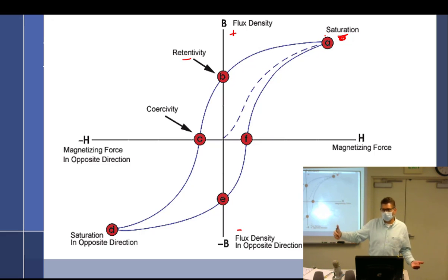Now, some material, like these harder crankshafts or things that are hardened that have high retentivity, if the retentivity is way up here equal with saturation, then you've got it made. You can keep doing it over and over and you don't have to apply the power, but that's not usually the case. Usually retentivity is a little less than saturation. So anyway, we apply the power. We can apply the fluid at that point. We've done it at the saturation level. Remove the power, it pops down here to retentivity, and there it is, just hanging out at retentivity.